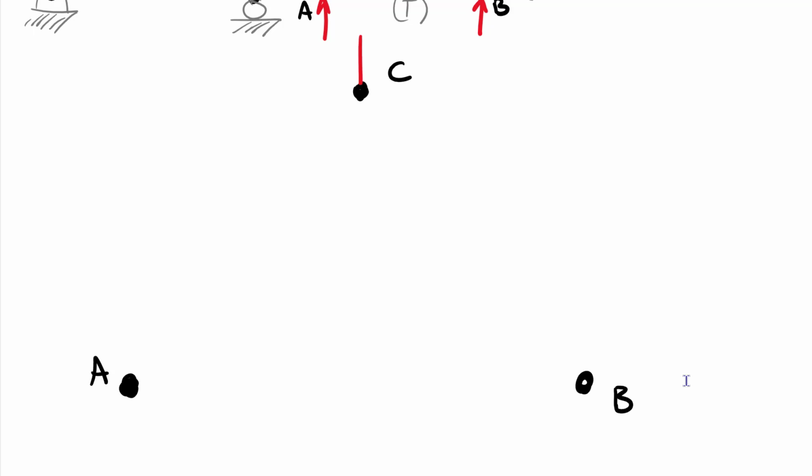Let's go ahead and add our applied forces. So here's my applied force F. Add our reaction forces. I'll label them this time. Call this one AY, this one here AX, and then a roller force giving us a vertical normal force of BY. At this point, I'm assuming the direction of these reaction forces, same kind of thing. I'll check those with my math.